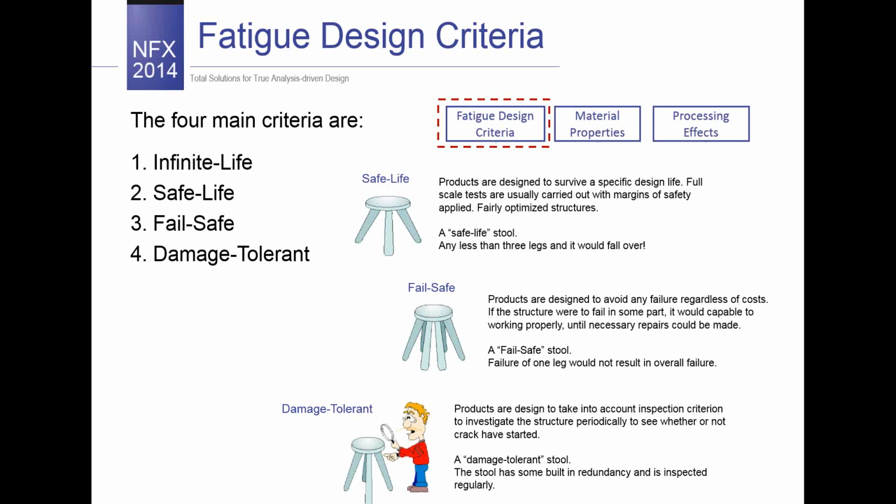This is the oldest one, and it requires local stresses or strains to be essentially elastic and safely below the fatigue limit. For example, for parts subjected to many millions of cycles, like in engine valve springs, this is still a good design criterion, but may not be economical in regard to excessive weight of structure. I'm talking about the competitiveness at this moment, and due to that it's not practical in many design cases.